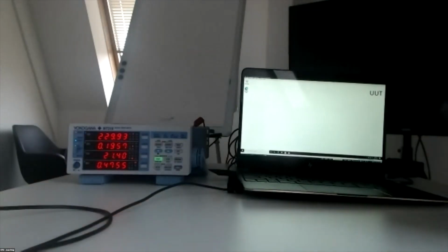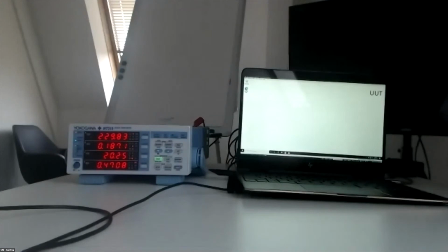Yuan, could I just mention one thing very briefly? Just for participants' benefit, this is connected to mains power in Germany, and it looks pretty good. You guys are right at 230, but there will be some distortion and anomalies in the grid. For the actual test in a laboratory environment, you'd want to have a conditioned power supply to make sure you're getting clean sinusoidal at 230. Yeah, of course. Thanks, Mike.